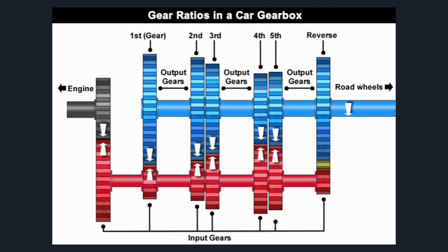So in this diagram, we can see the gear mechanisms in a car gearbox that output different forces based on whatever gear you set. And as you can see, it's compounding different gear sets that affect the shaft at different times, depending on which is selected. And as you can see, it's not so uniform. It's not one set of gears on the input shaft matched with different gears on the output shaft, which makes sense, right? The output shaft can't be in different locations, so it has to be in the center. Therefore, there's a set total distance you can have between the two shafts. So you change the gear sizes to accommodate and create different output forces, which is a really interesting concept. And this is obviously a simple diagram, but it effectively shows how one single object or one group of mechanisms can employ a set of different gear ratios. Now let's go on to our next slide.